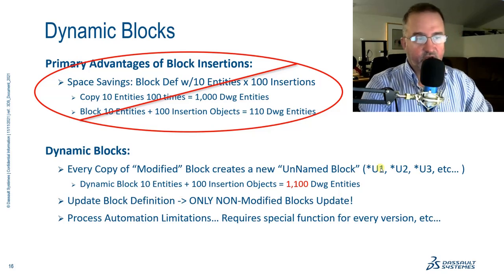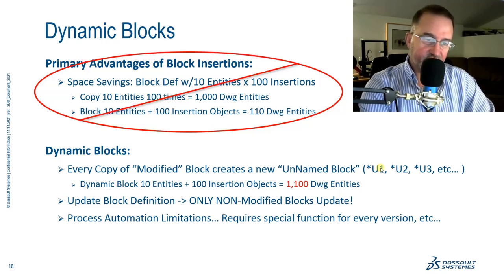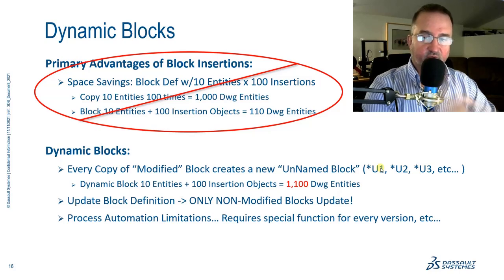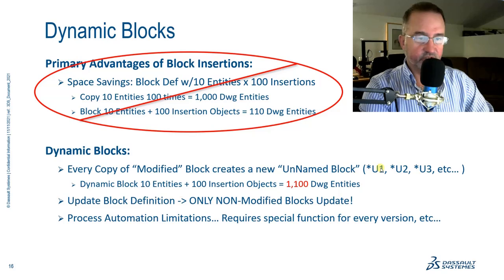So that's just my take on dynamic blocks. As you can probably imagine, because of the thousands of lines of code I've had to write to manage these things, they're not my favorite. There are some cases where they're really cool and they can do some really creative things, especially with some parametrics. But honestly, if there's a way I can achieve the same thing with 3 or 4 blocks instead of one crazy block, it's easy. Those 3 or 4 blocks are much, much easier to manage.